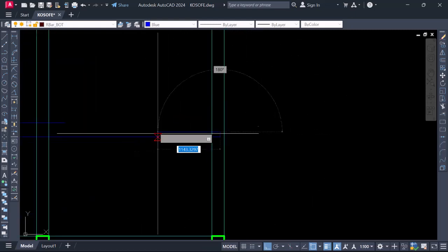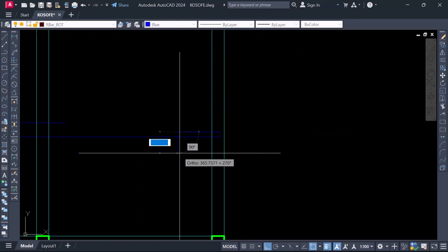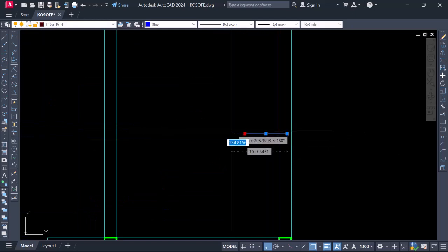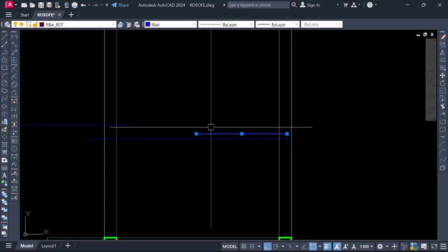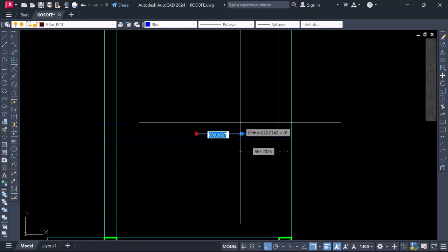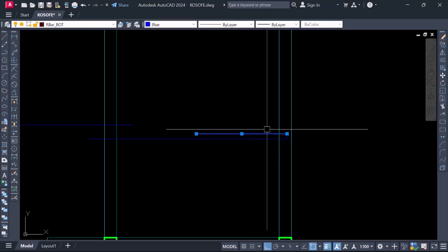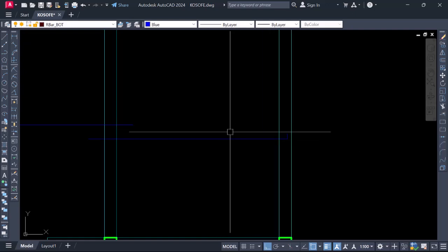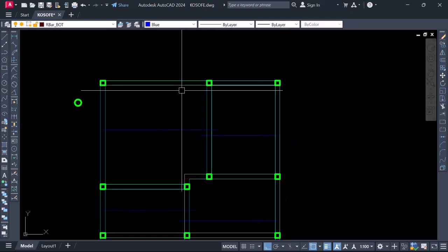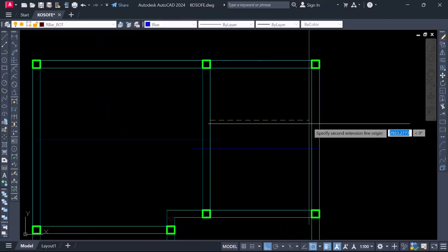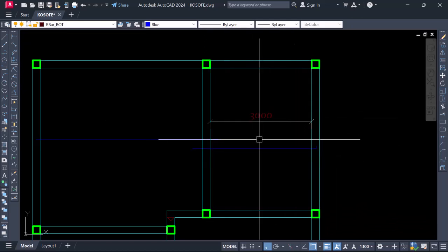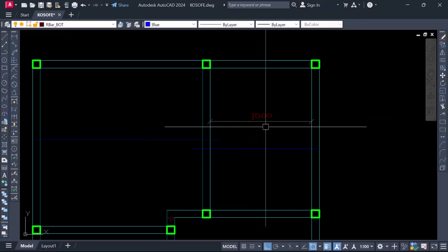We don't just want to add the length of this reinforcement. Like I always tell people in engineering, there's a formula to everything. You don't just want to drop it anyhow. Another person can choose to do this, another person can choose to do that, as the case may be. You don't do so. What you're going to do is check from our code. We have a nominal length for our top reinforcement, which is 25% of this span, or 30% of this span, within 25 down to 30. Whichever you want to use is still better for you.